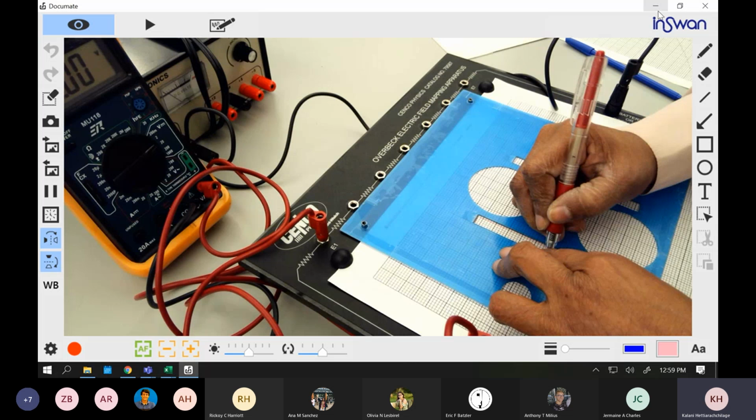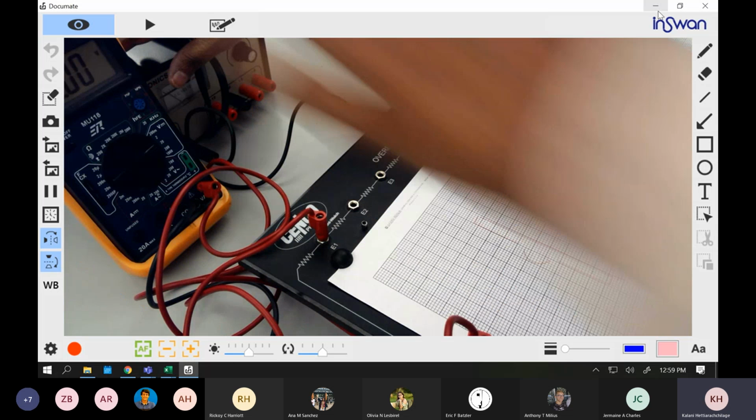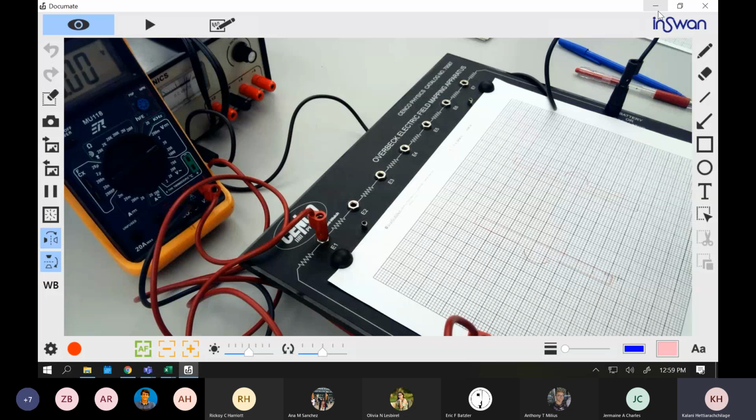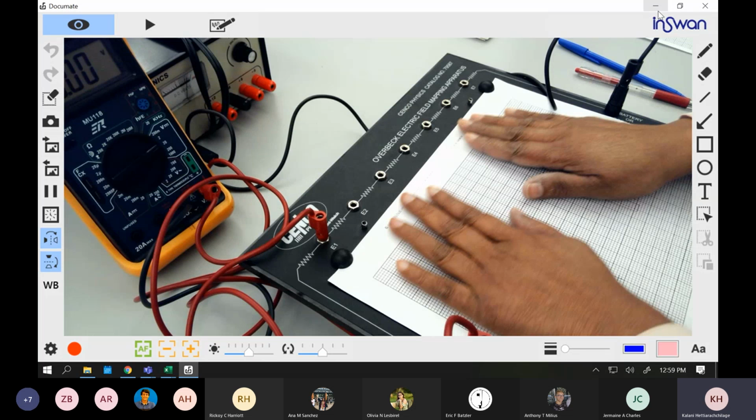Then you have the parallel plate. Okay, so now you can switch on the power supply and give around 10 volts as we used earlier. For the parallel plates, we know that our equipotential lines are just vertical lines, right? So it will be easier than the earlier one. We're going to repeat exactly the same thing. Go with the probe and find the 0 voltage point closer to your left one, and then keep moving to each E point.